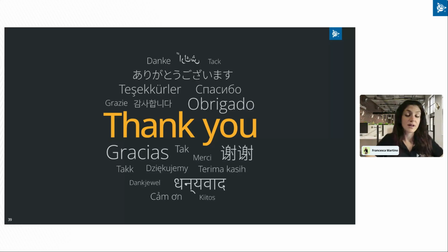SketchUp cannot create point clouds itself, but there are a lot of applications that are capable of doing so. If you're talking about using an iPhone or an iPad Pro, you can download an extension, for example, Scaniverse and Polycam. Scaniverse specifically is a free extension that allows you to use the LiDAR and therefore scan the space and create a point cloud.